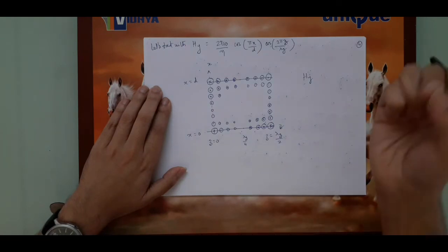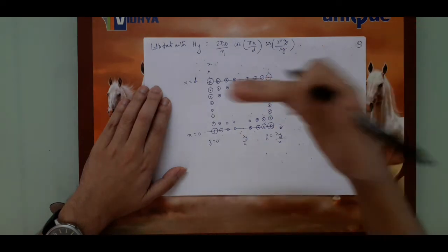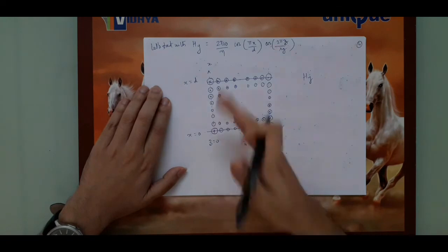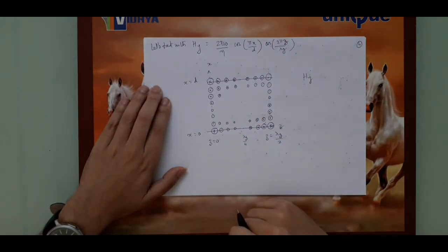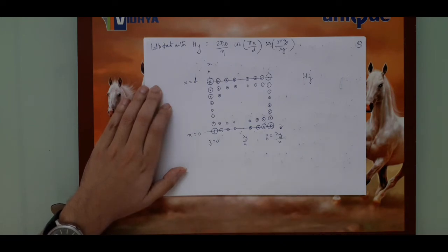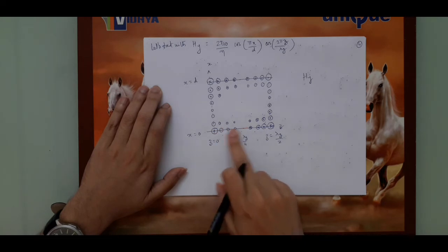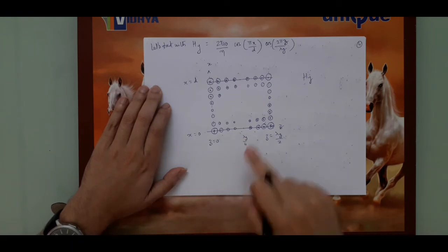And using that current probe, I can actually measure the surface current, and from that I can back calculate and say, now these are the points at which the fields will be maximum. This is the point at which the field will be minimum. So very similar to a transmission line, you can see that the field maxima and the minima of 0 are separated by lambda by 4.